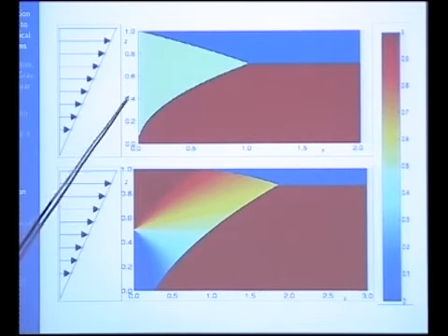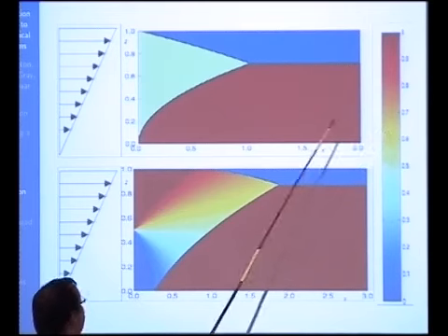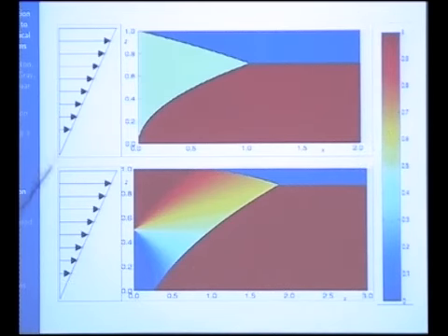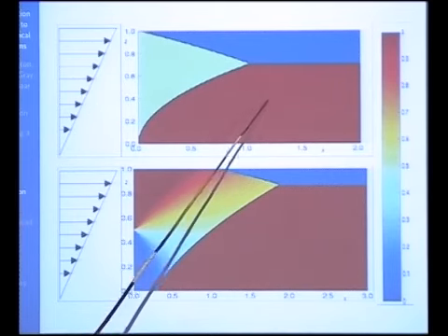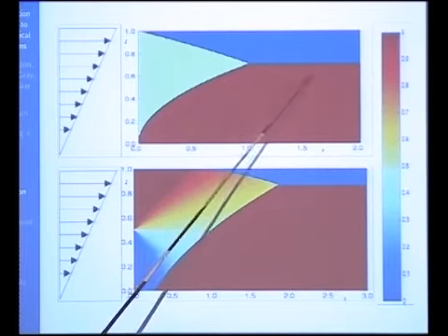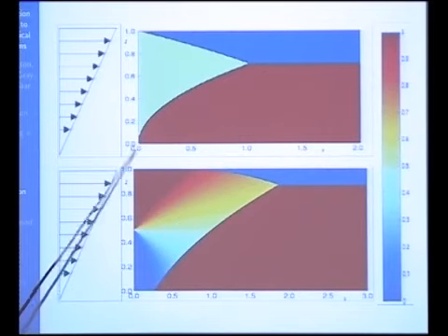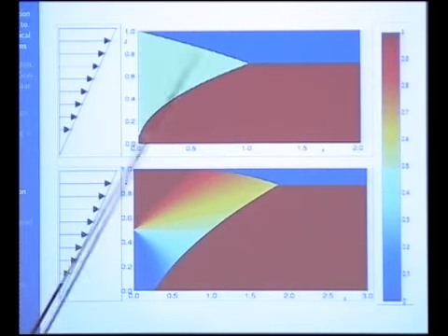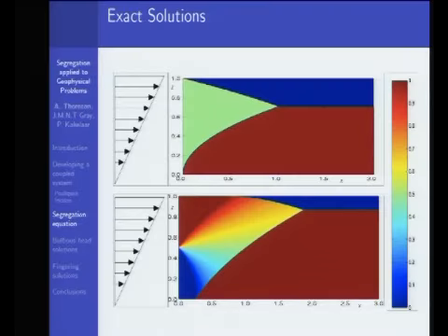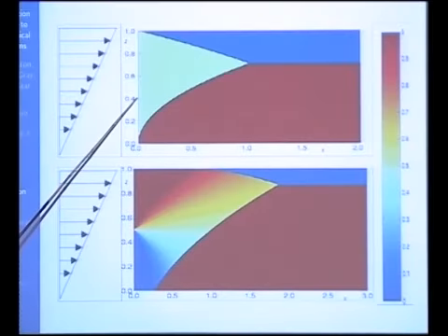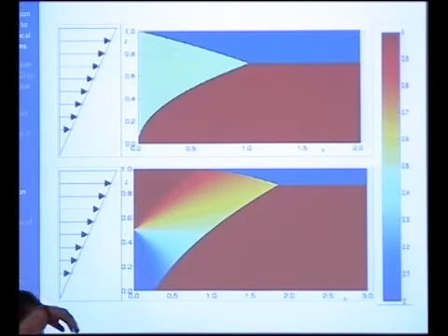So this is just considering the flow out of a simple hopper. We're assuming there's no cross slope velocity, and the vertical velocity is something like that, and we get these solutions. Here, we're plotting the volume fraction of small particles. We're flowing out of a hopper where there's mixed material, and as this material flows out, a long way downstream it has segregated, with the large material on top and the small material below. The solution consists of three shocks, two shocks here and one shock there.